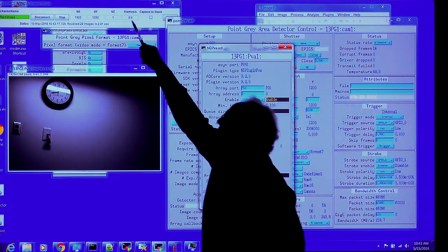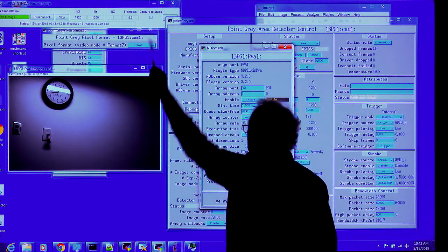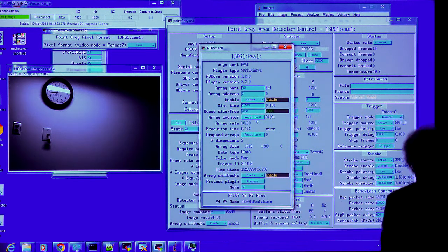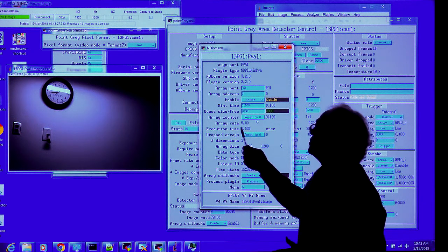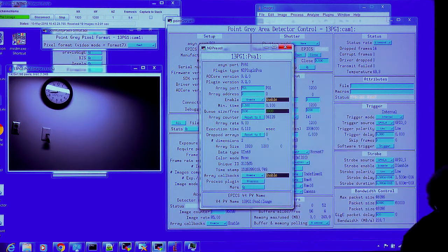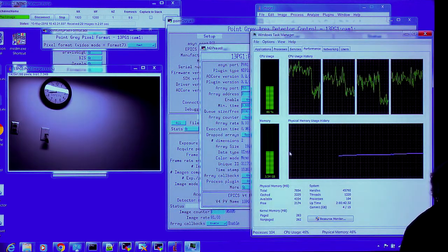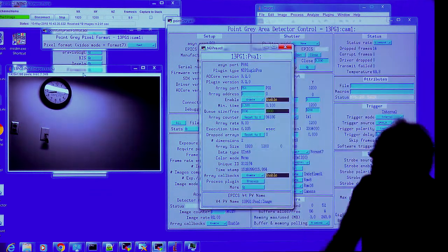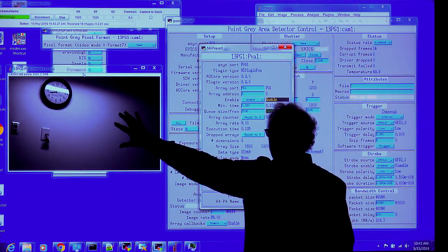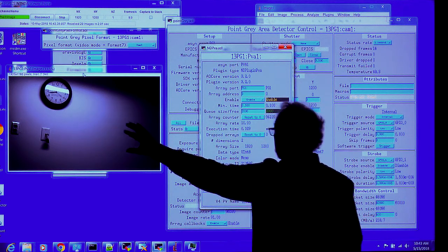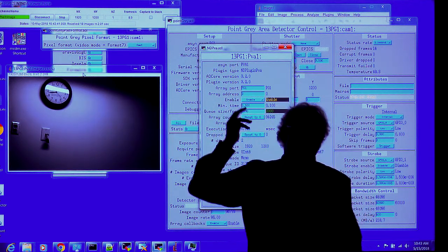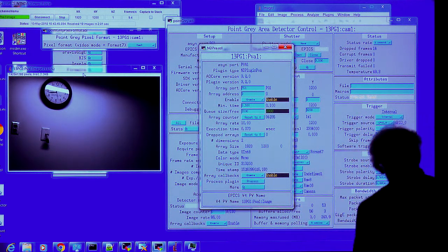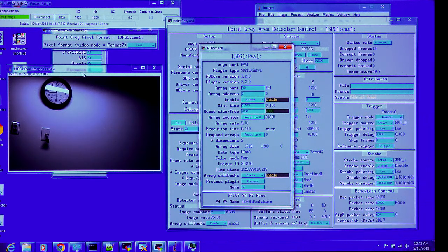And now this guy is keeping up, right? It's running, it can keep up at 10 hertz. So that's sometimes a useful thing to do, because I've now probably reduced the CPU time on the system significantly. And do the users really care that this is only running at 10 hertz? Probably not. So slowing this down is often a good thing to do. Saves you network bandwidth and CPU cycles.